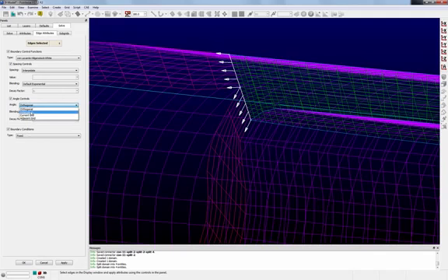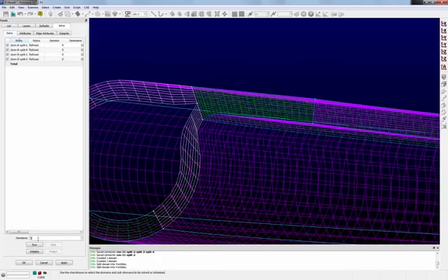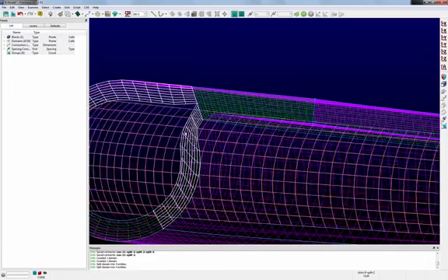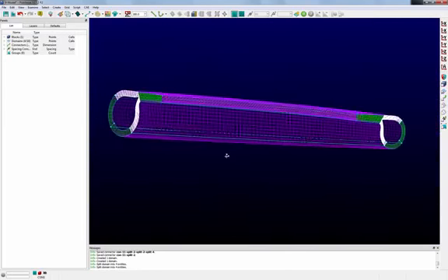So instead, I'm going to change that from orthogonal to interpolate. Then going to go over to Solve and run it for 5 iterations. And you can see that even after 5 iterations, we now have much better orthogonality here, and we have a much higher quality grid overall.